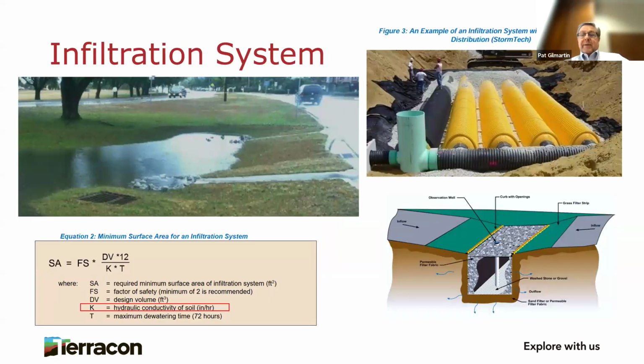An infiltration basin can be an open basin, trench, or a below-grade pipe system. It needs to be above the groundwater in order to stay dry in the long term. I guess if you can design a precast box, you might be able to put it below the water table, but you might want to design it for buoyancy.